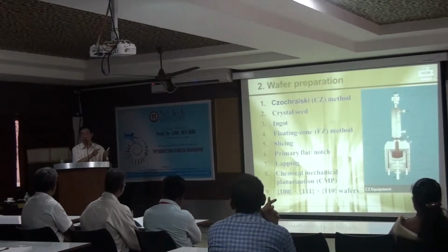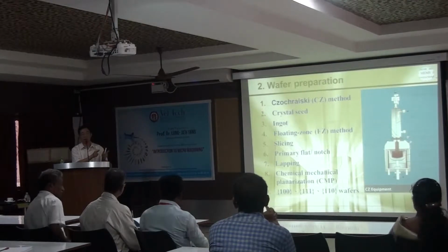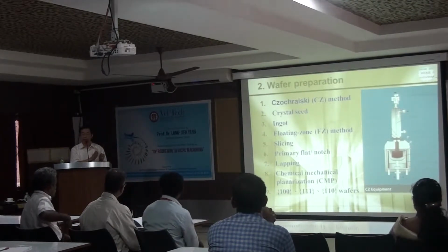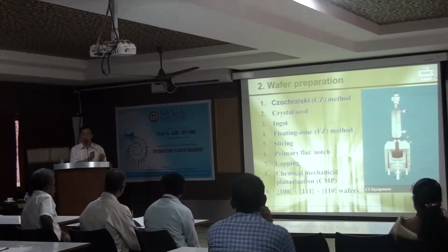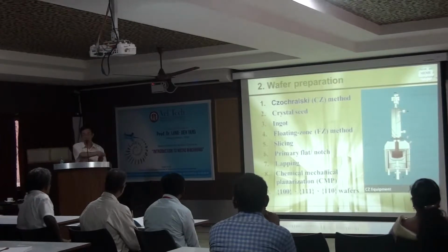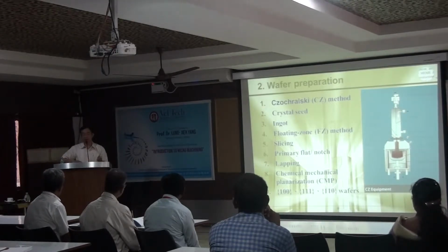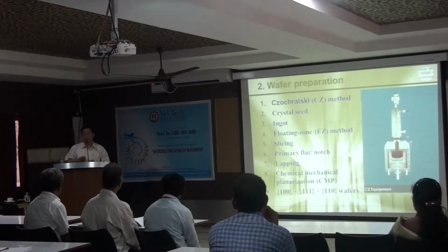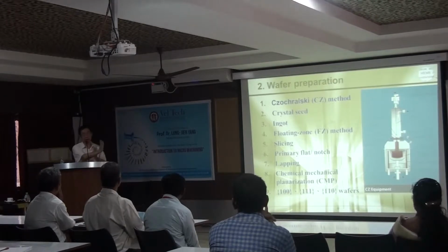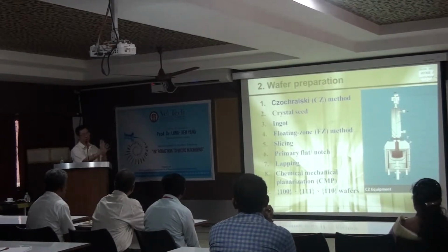We used a diamond knife to scrape the surface, like cutting glass, because silicon is a very hard, brittle material. So you cannot use an ordinary cutting method. You can use the method like cutting glass: you scrape the surface, and with a little bit of excitation it will break automatically along what we call the natural cleavage plane.